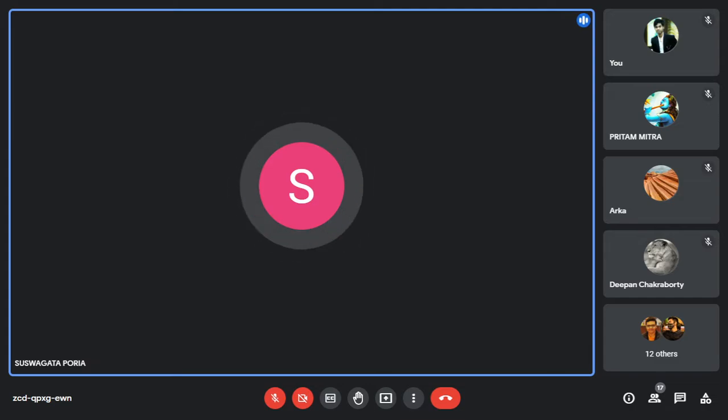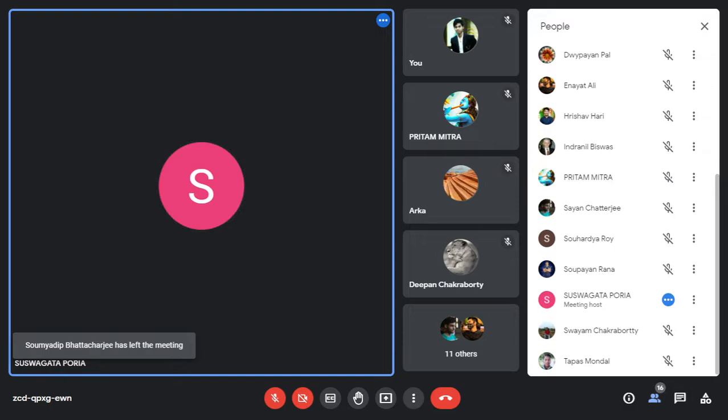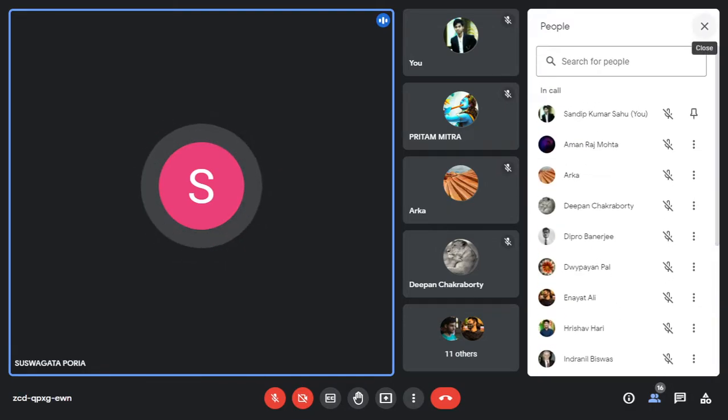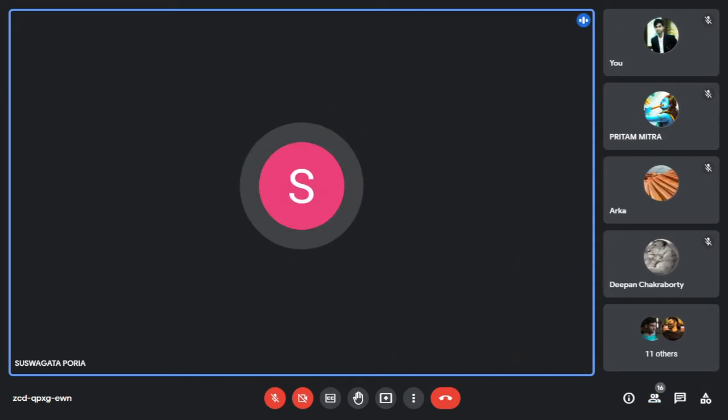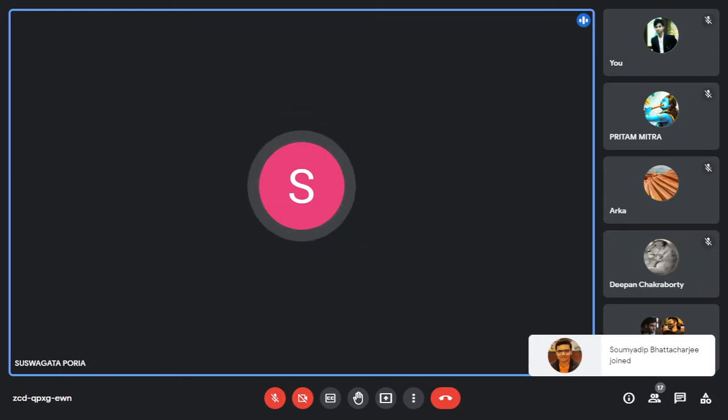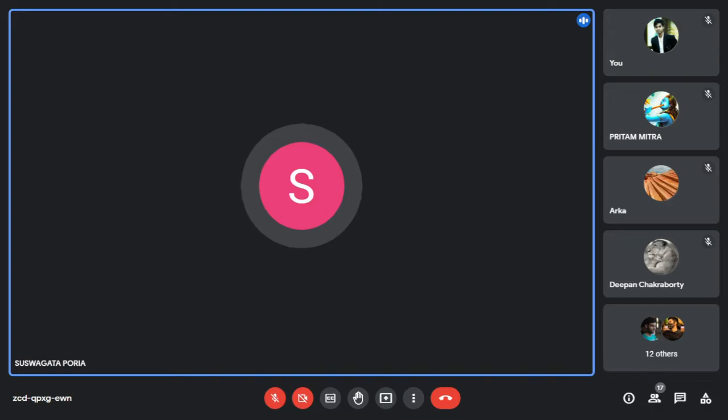This is one thing. The second thing is that some of you asked me about hatching, where we have to do hatching and where we should not. I already wrote some lines in your classroom and uploaded an image where you will understand that the drawing I have given in the assignment was a half section. So the total drawing has not been cut. Only the left side portion has been cut. So when you do the part drawing, only the left-sided portion will be hatched. The right-sided portion will not be hatched.